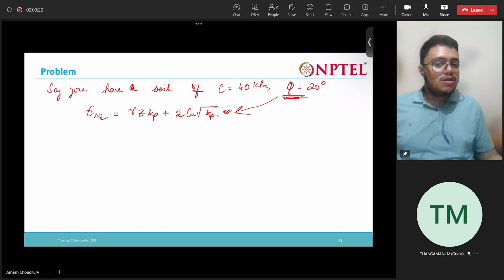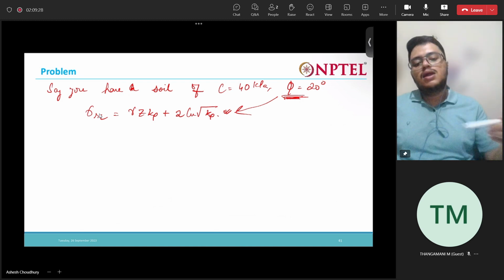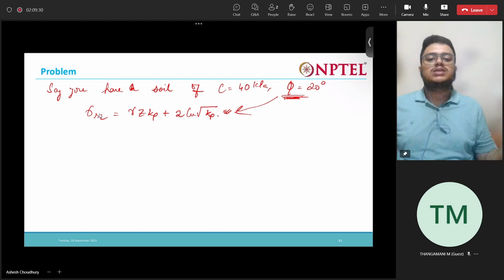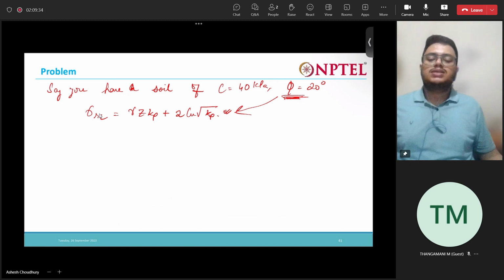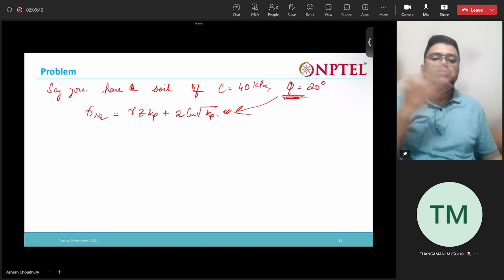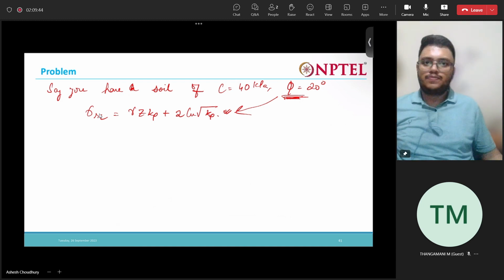That was the benefit of vacuum consolidation. We also did some rough calculations, and we saw that in the clay layer, at all depths, the increase in effective stress was about constant. So we are just making use of the atmospheric pressure to induce effective stress so that this consolidation happens, right?